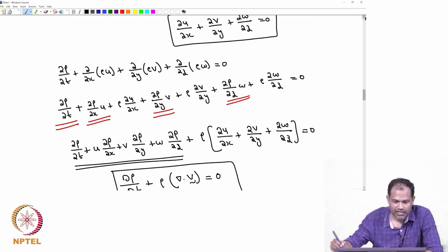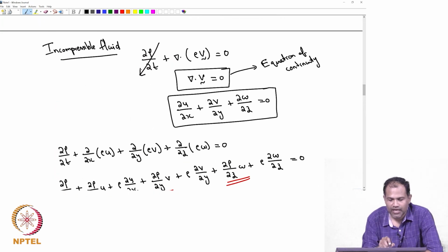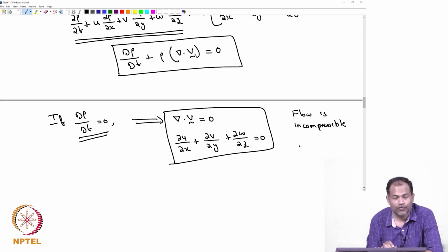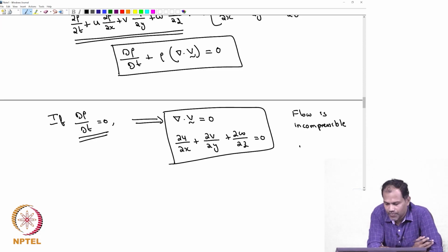So, earlier we said that the fluid is incompressible and we threw away all the terms containing derivatives of rho, and then we found that you basically get divergence of V is equal to 0. But you will also get divergence of V equal to 0 if you find that following a fluid element does not change its density. Most often, the cases that we will consider would be either that the flow is incompressible or that we take the fluid to be incompressible, and in either case we will have divergence of V equal to 0, and that is the equation that we will use.